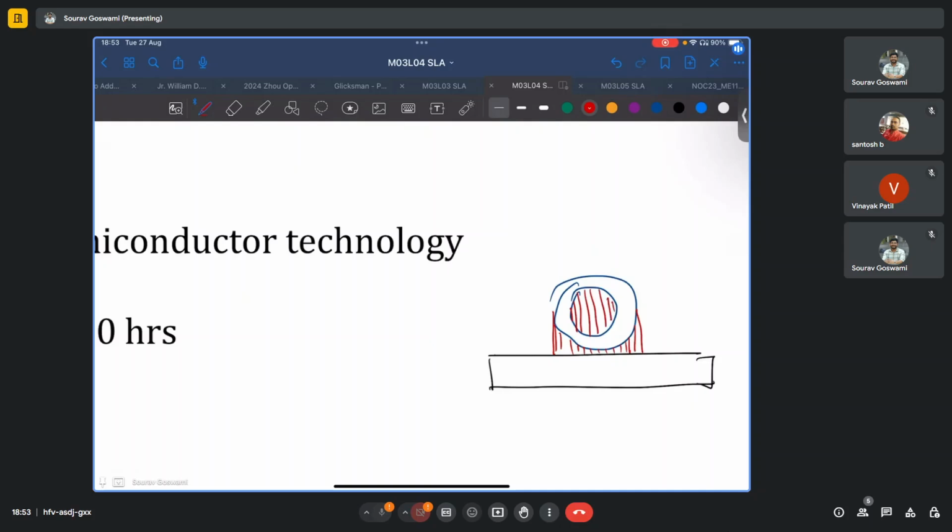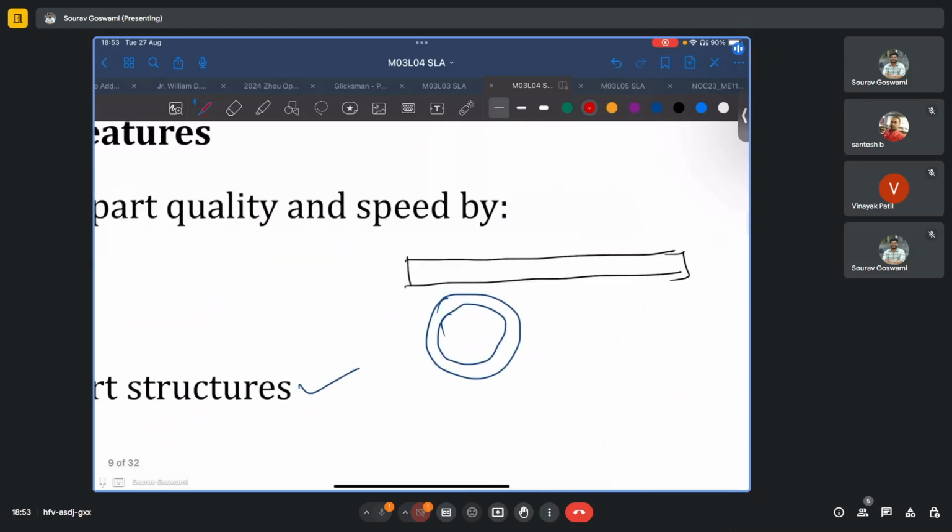And since this hollow sphere is closed, I will not even have any recourse or any method to remove these support structures later on. Now consider building the same geometry upside down. Support structures will be required here, but that's about it. No more support structures are needed.